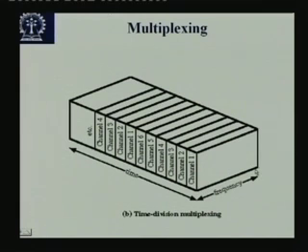The same multiplexing scheme looks like this. So, this is the frequency, the same plot. If you remember in the previous diagram, when we were doing FDM, we were slicing this channel in this fashion. Now, we are slicing it in this fashion, that means time is divided. So, channel 1, channel 2, channel 3, channel 4, channel 5, channel 6. They get the entire frequency range for a small burst of time, and suppose only 6 channels are being multiplexed, then after 6 it again becomes the turn of channel 1. So, channel 1 sends the first burst of data using the entire frequency band during this time period, and then during this time period channel 1 is not sending anything. So, it is quiescent. Time is getting divided in this fashion, and this is why it is called time division multiplexing.